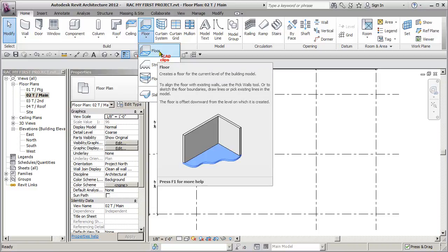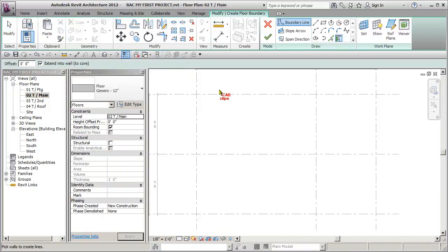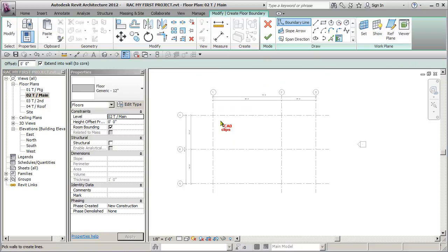As soon as we click this, we're going to go into sketch mode. Watch what happens. Click. All of a sudden the screen changes a little bit. We see our contextual tab here, which is going to show up when we start to draw stuff. But the biggest hint here is the big red X and green check mark. You know you're in sketch mode when you see these two guys inside of here, which means that you have limited availability. Everything else kind of becomes grayed out.